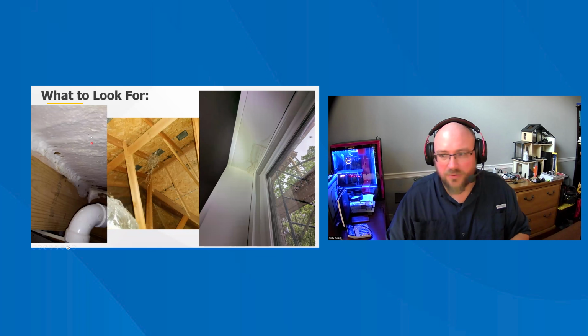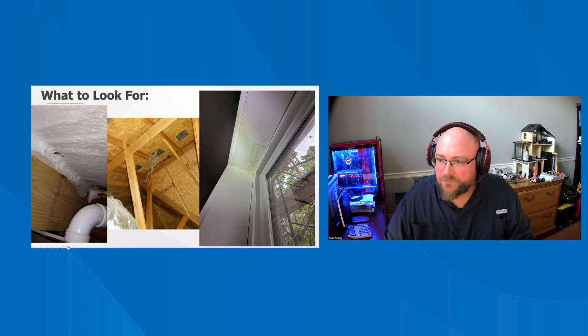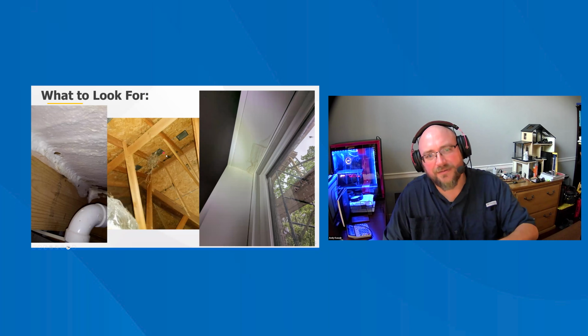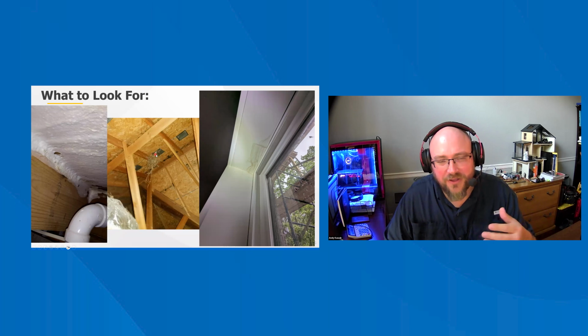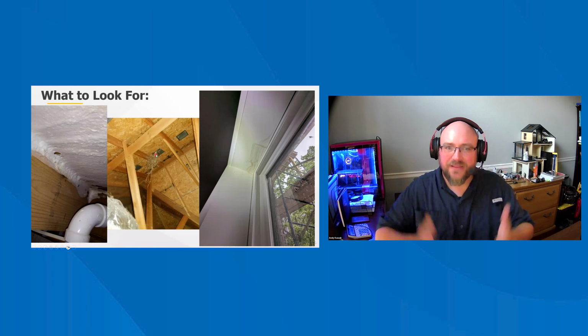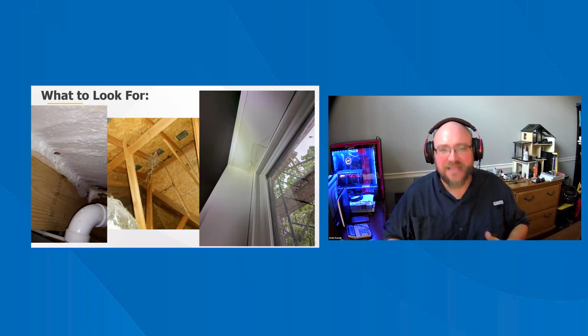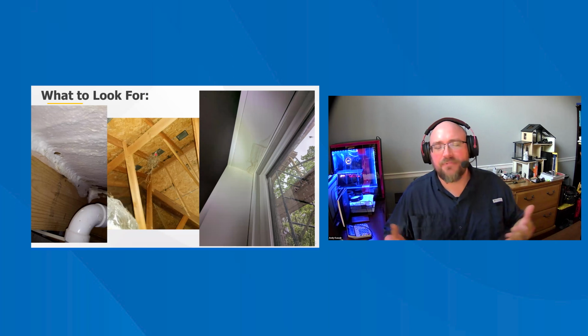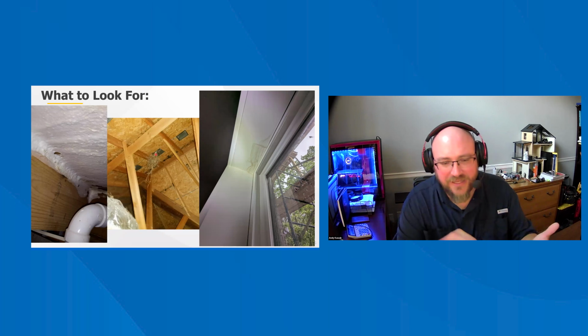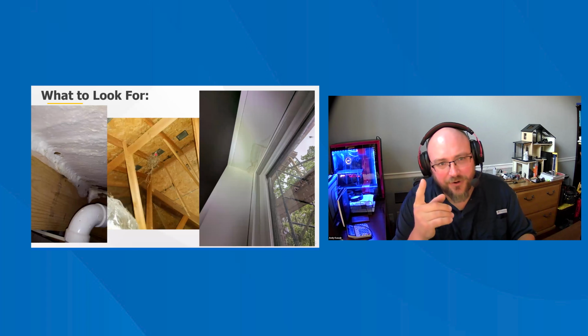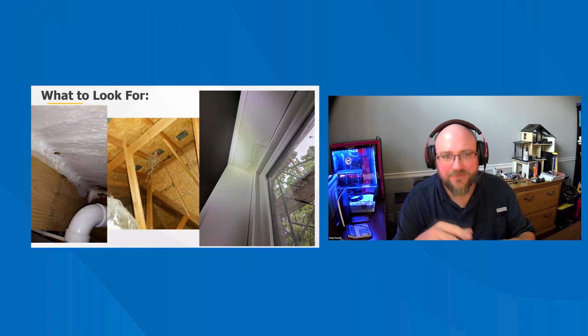created this mold colony. Here is an attic picture with box vents in the attic, and this is very common because you have warm air that's expelling out of those box vents, basically any penetration. So you have your bathroom vents, your dryer vents, your box vents, any type of ventilation.